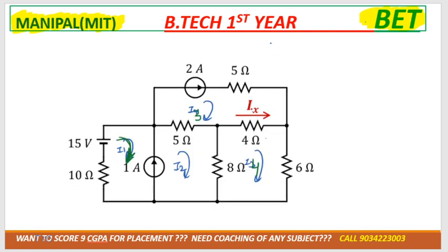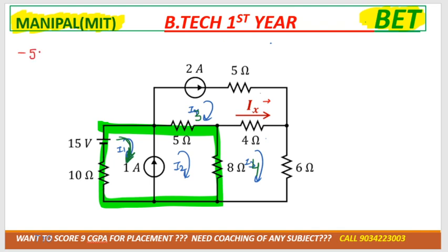Now for this we need to calculate ix by using mesh analysis. So the first equation would be through the super mesh. This is the super mesh. So the first equation would be minus 5(i1 minus i3), then minus 8(i2 minus i4), minus 10 i1 plus 15 is equal to 0.